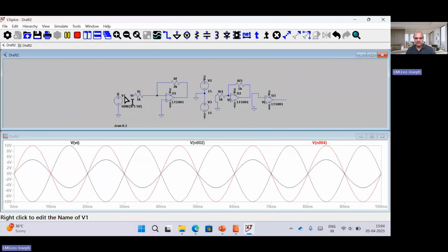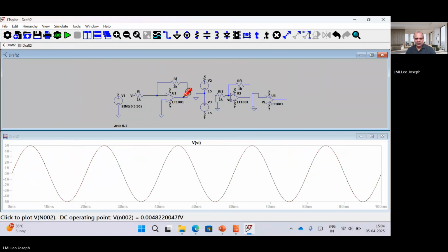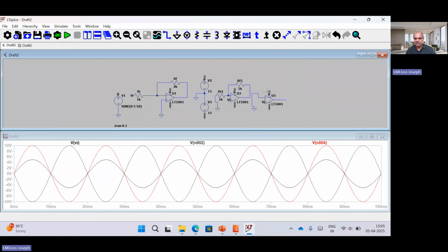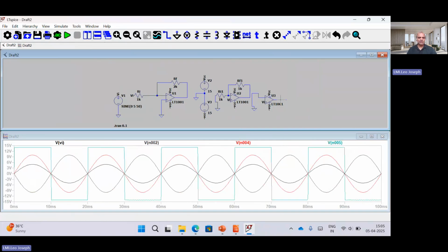Now once again I want this circuit, I want this output connected. You can see here what is the difference in the open loop mode. It is not giving oscillations, it is going directly. I am giving 5 volt here, but irrespective of my voltage, it is directly going into saturation. It is uncontrollable. But where is it going to be used? It is going to be used for square wave generation.